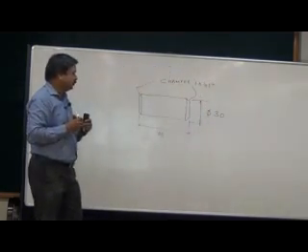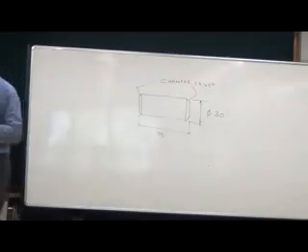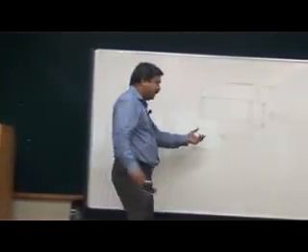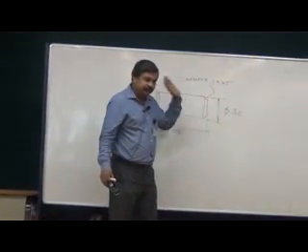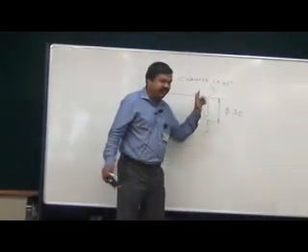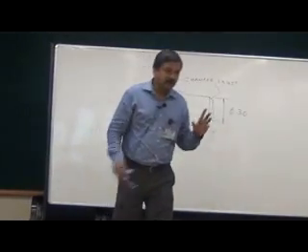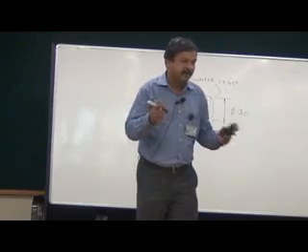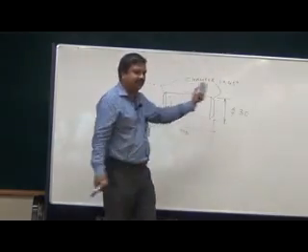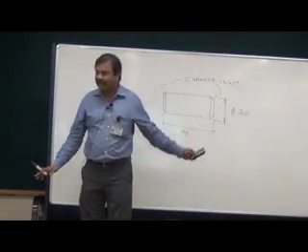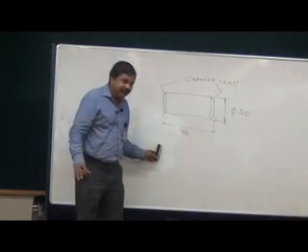Okay. So all the dimensions are given. So I have a shaft which is of length 100 mm, diameter is 30 mm. You have chamfers at both ends. Chamfers eliminate the sharp edges and also they make your assembly job easier. So you have the drawing ready.